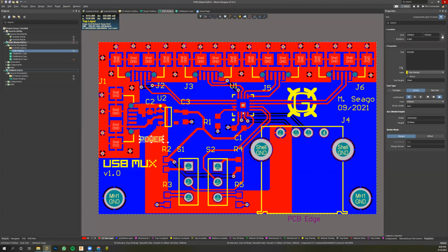You could just put vias. That's fine as long as you label them. But test points, test points, test points. Put a lot of test points. I can't emphasize that enough. It will irritate the snot out of you if you don't, and then you have a problem where you can't probe something. Yep, I think that's it.